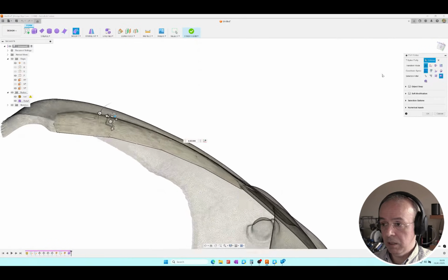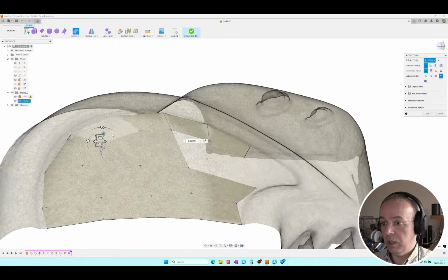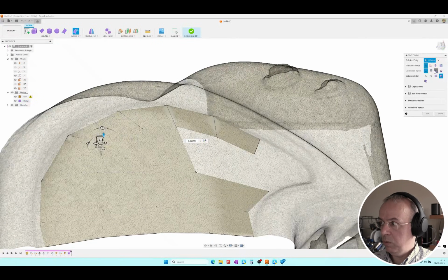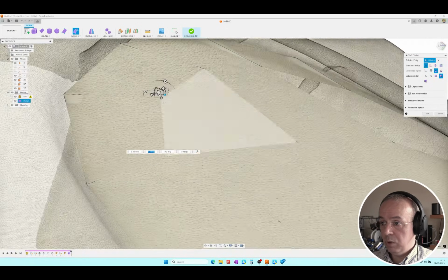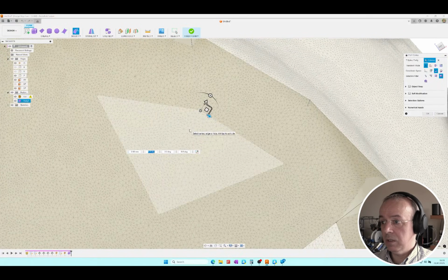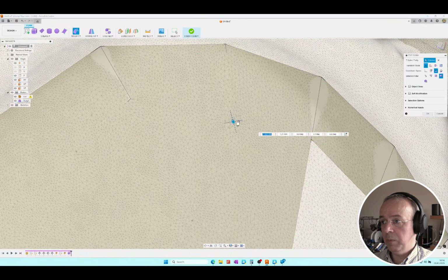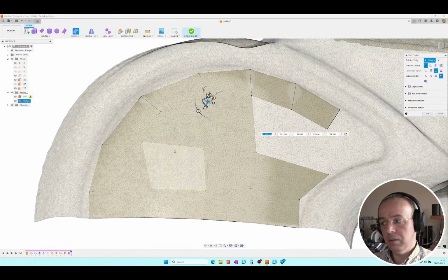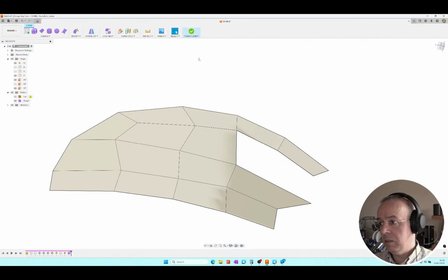Avoid adding more geometry, because if you do, you'll need to add it to the rest of the piece. While there's no inherent problem with this, it will increase the model's complexity. With a high number of vertices, you'll eventually need to use more advanced tools like soft selection, which moves elements within an influence area that dissipates. And here's this part. Let's accept it and even hide it, at least for now.